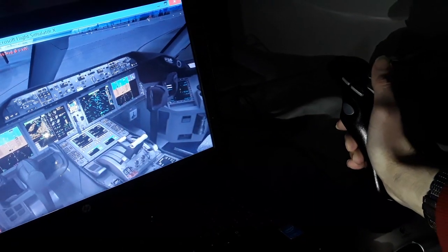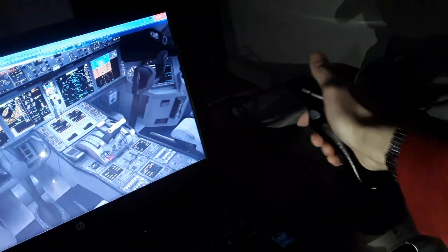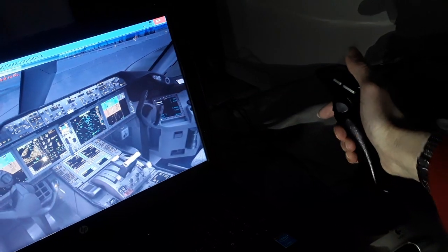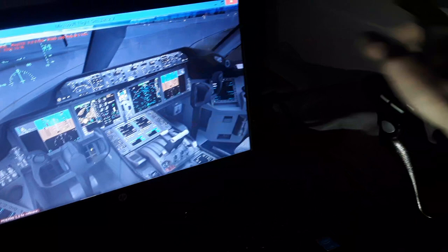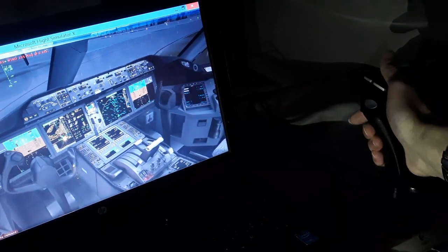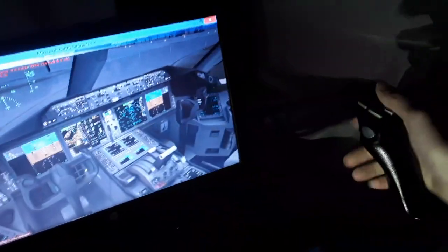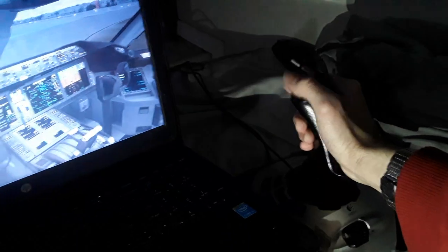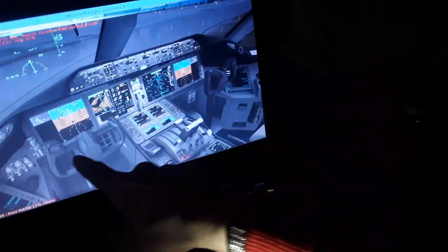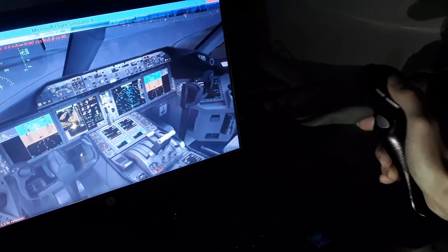No problem with that. Also in the Boeing, you can see both the captain and the first officer controls are interconnected and move together in flight. You need to use some force in the control column or the control wheel, the yoke of the Boeing 787, to take either side and override the other. In the Airbus you have the side stick priority button. Also both the Airbus and the Boeing have the rudder pedals interconnected, no difference to that at all.